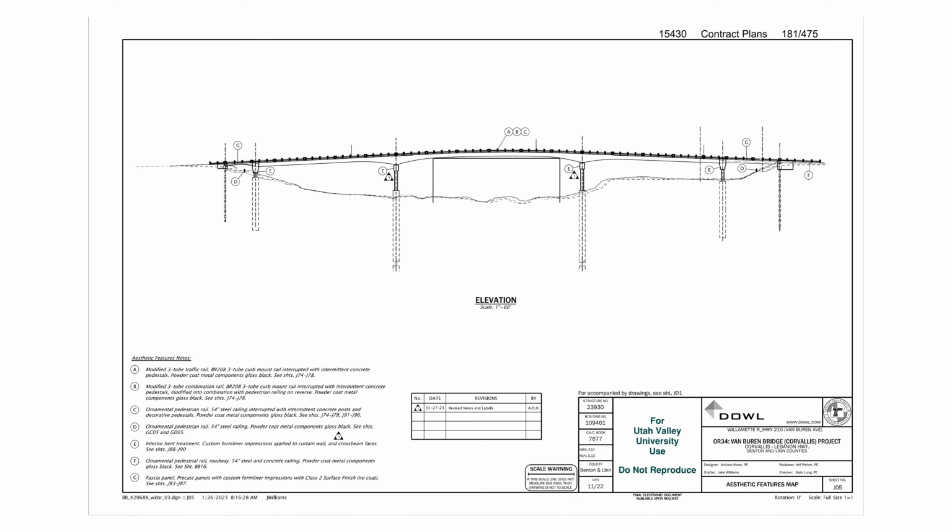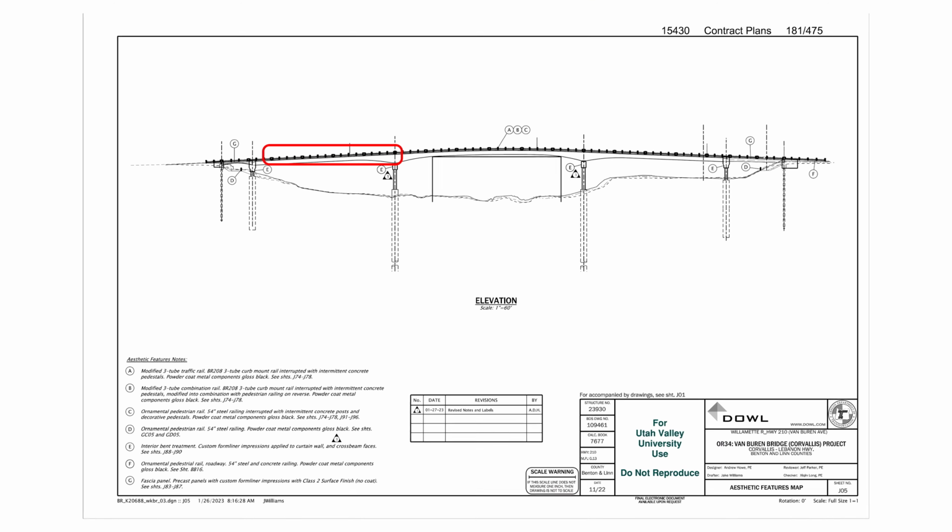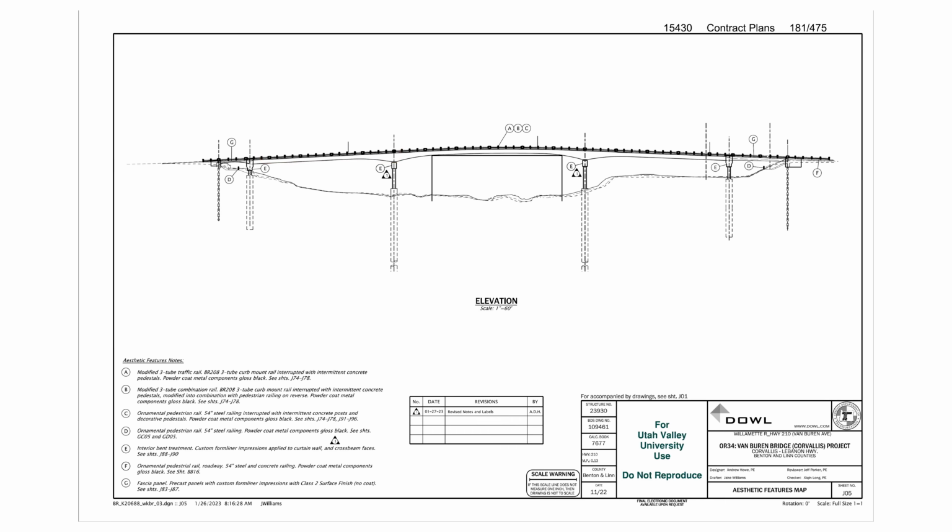But it's interesting how that will just work structurally, because if you put a load on that first span, the rest of that steel girder is going to bend a little bit, even the spans that aren't loaded. And so if you have a failure in one of those girders, you're going to have 4 other girders that can take that load, but also the remainder of that girder is also still there. So that's kind of an abstract look at redundancy, but that's one type of redundancy the new Van Buren Bridge will have.